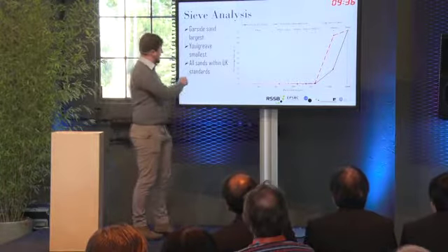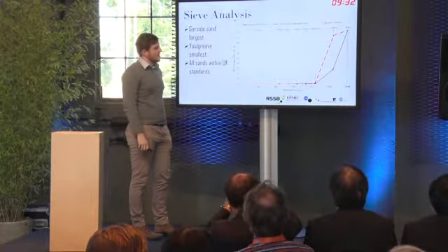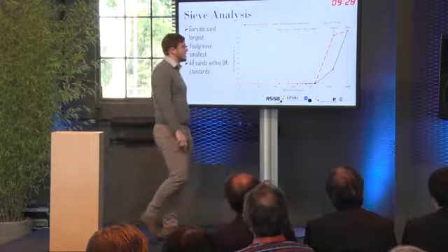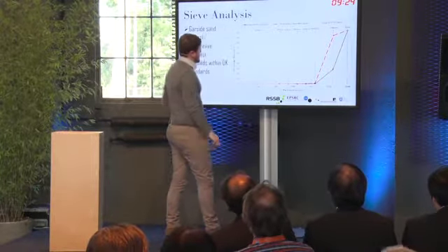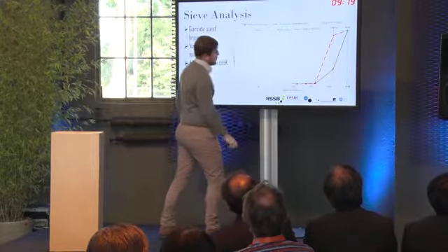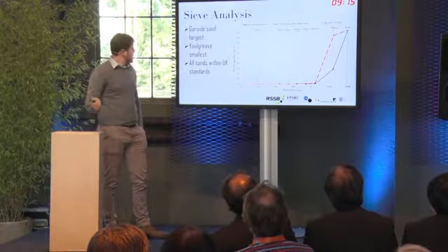All these sands were within UK standards, I believe also all within German standards, and some but not all were within French standards. So you can see here, this is just a percentage passing graph, so they all come up quite steep, quite uniform sands.